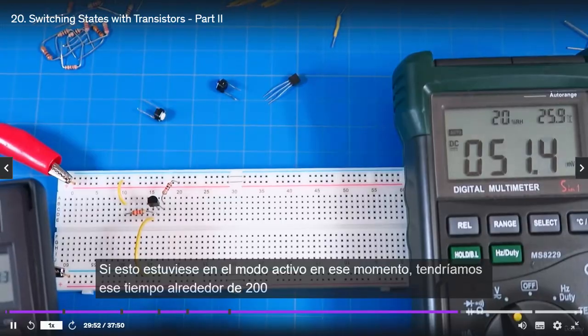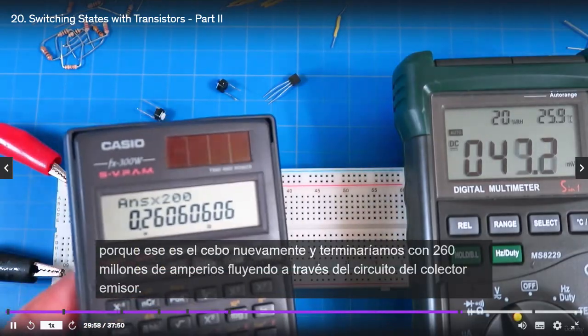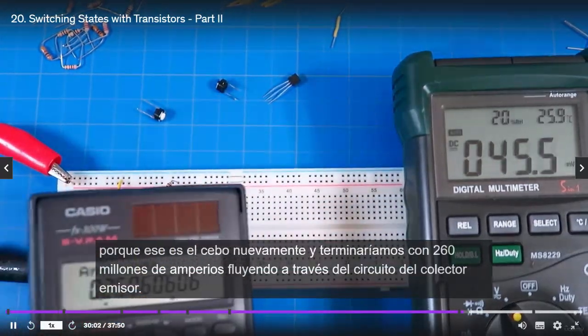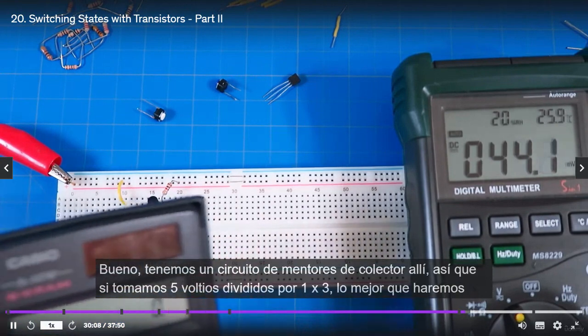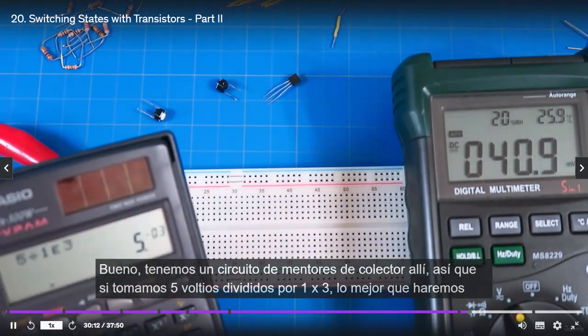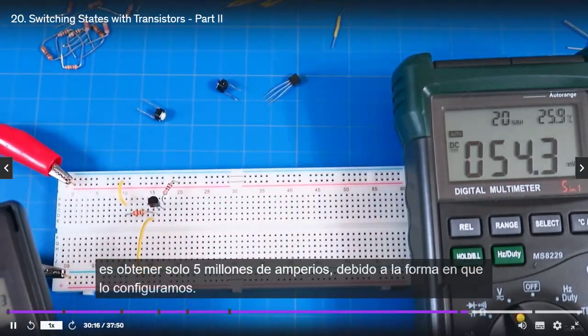If this was in the active mode, right, then we would have that times about 200, because that's the beta gain, and we would end up with 260 milliamps flowing through the collector emitter circuit. But we can't. Why? Because what's the best we can do? Well, we've got a 1K in the collector emitter circuit there. So if we take 5 volts divided by 1x10^3, the best we're going to do is get only 5 milliamps, right? Because the way we've set this up.